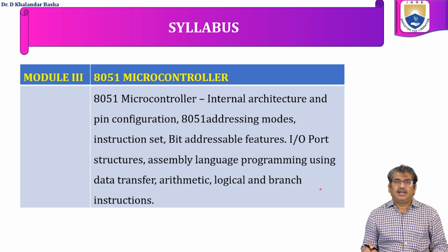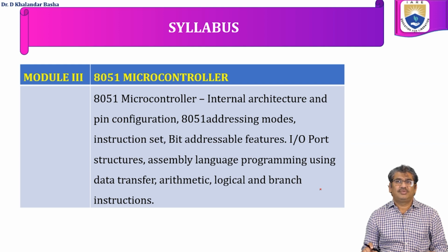the various addressing modes supported in the instruction set of the 8051 microcontroller will be studied under this topic. Instruction set: the various instructions like data transfer, arithmetic, logical and control transfer instructions we are going to study under the instruction set. The bit addressable feature: when you are accessing memory, usually we send bulk bits, like 8 bits, for each data transaction, whereas in the 8051 microcontroller we have a facility of accessing a particular bit also. A few memory locations have bit addressable capability, as well as a few registers for setting or resetting a particular bit of a few SFRs, that we will see under bit addressable features.